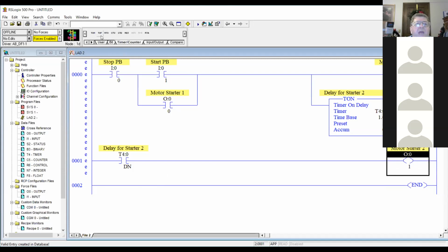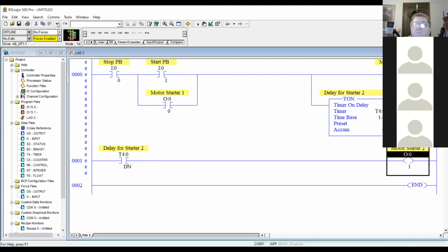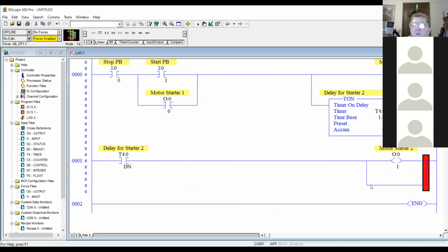So we go in timer counter and we have, wait a minute. I did that wrong. I should have done a branch. I hit undo. We're going to do a branch and then a timer. So branch and then another timer. See, all this stuff up here looks the same, doesn't it? Yeah. All of your instructions look the same. I mean, they are the same.